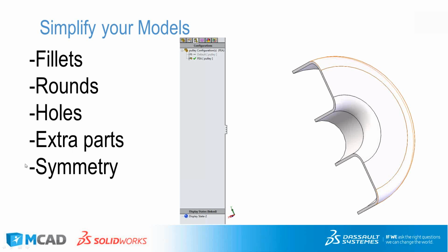Finally, one thing to really keep in mind is that symmetry is of utmost importance when you're doing these modeling challenges. Any time that you can cut the model into a symmetric piece, you've made your computational domain half as big right off the bat. And that's so you can have double the mesh for the same part and get a much finer detail for the same solve time. And it's nice to note that if you have more than one plane of symmetry, you can use all of those planes of symmetry. So if you had a part that was symmetrical across the front, right, and top plane, you can theoretically divide it into a 1/8 of the original part using symmetry constraints and solve that one little chunk to save yourself a lot of modeling effort and a lot of meshing headache. You know, especially if there was a lot of contacts, doing 1/8 of the contacts is totally worth it if you're trying to save time and get your model done at the same accuracy.